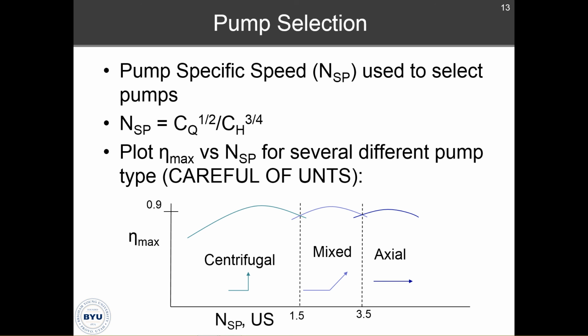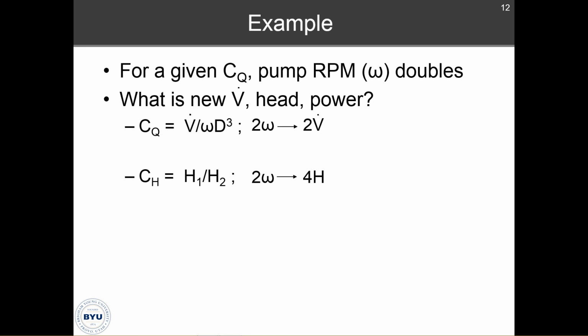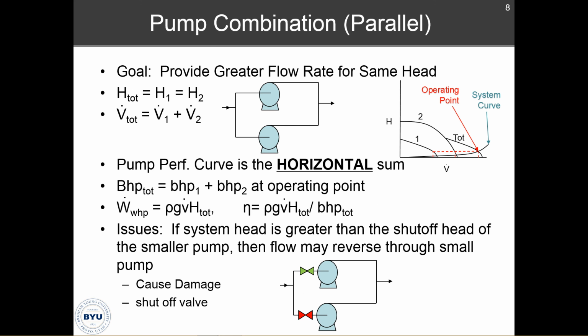Simple in concept, and pump networks, where you're going to be looking at how many pumps you want in series or in parallel. I highly recommend that you really look over and understand how to add pumps in series and parallel. It's the same as for pipes, but you're going to be dealing with the supply instead of the system losses. So again, as a review from last time, this curve that you see along the bottom represents the system curve. It represents the head loss or the pressure loss of a system based on the flow rate. This is exactly what you were drawing in the graphical method for the pipes. So this system curve shows you the total head loss for an entire system.